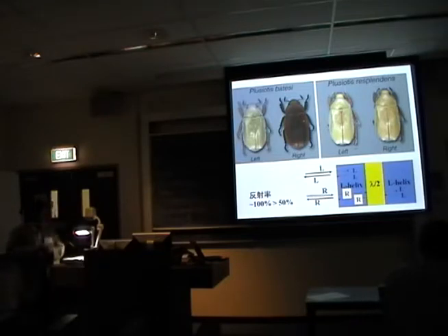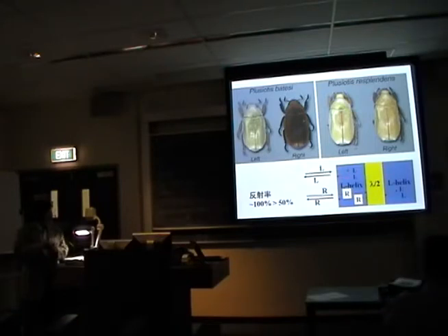In this case, if we input left-handed circularly polarized light, it is reflected back from the left-handed chiral liquid crystal immediately. However, right-handed circularly polarized light can pass through the first chiral layer. Because of the half-wave plate, right-handed light changes to left.